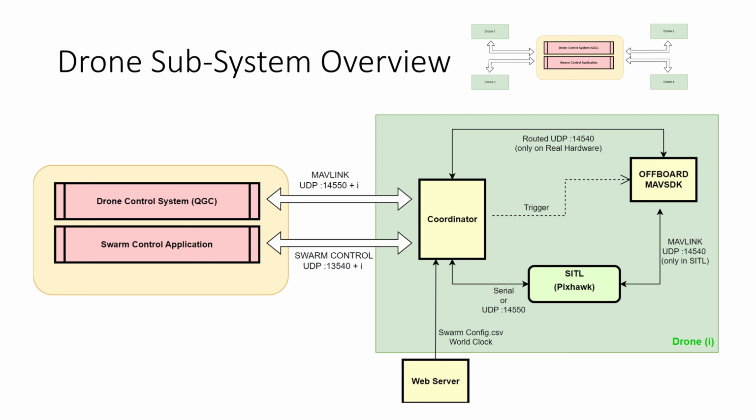Eventually, again, these two would be merged and we won't need to send our swarm control data on a different protocol or on a different port. We will make the mavlink-based telemetry packets and merge them together to only have one communication between the drone and ground control station. And also the swarm control protocol can be expanded to send data to all the drones.